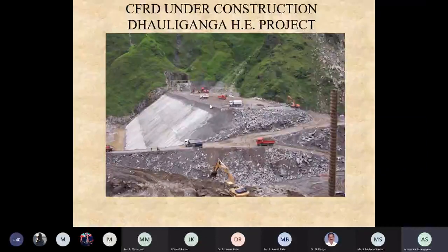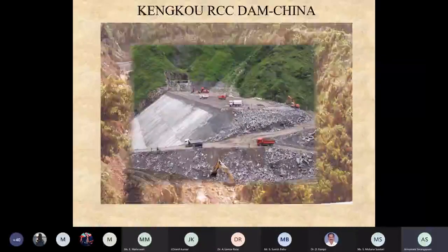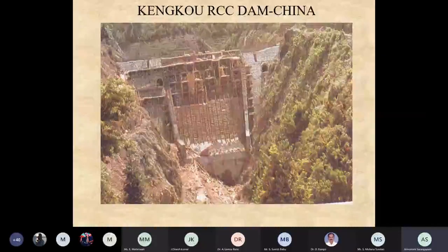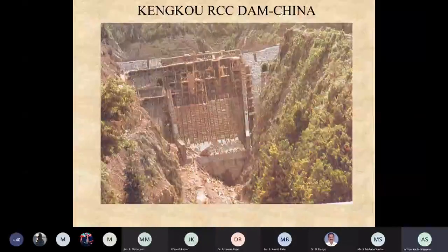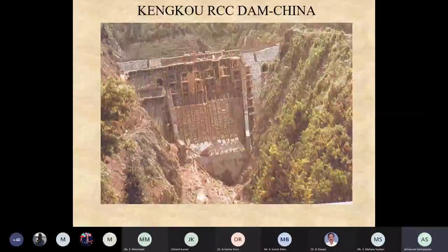And this is the RCC. In RCC the methodology of the dam will be somewhat different, but we will use concrete. We will pour a dry concrete. Here the concrete will not be wet. We will pour a dry concrete and it will be compacted. Roller compacted concrete, that's all. We'll pour the concrete and then just roll over it. So we will prepare the dam. This is an RCC type dam.